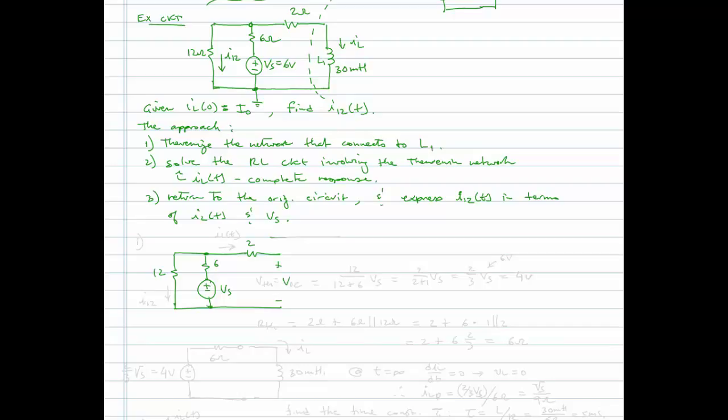So V open circuit is going to be the voltage here. V Thevenin is equal to V open circuit. When there's nothing connected to this network, we're not pulling any current. All right, and this is pretty easy to express. By inspection, I can see this is a voltage division of the Vs voltage across the 6 and 12 ohms.